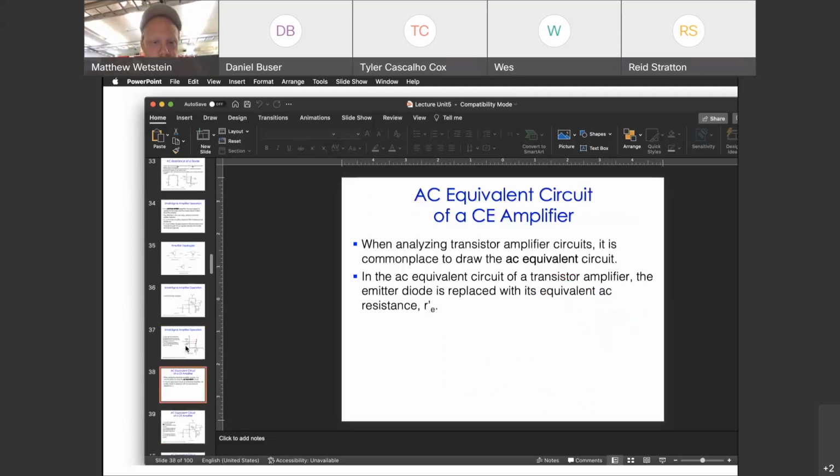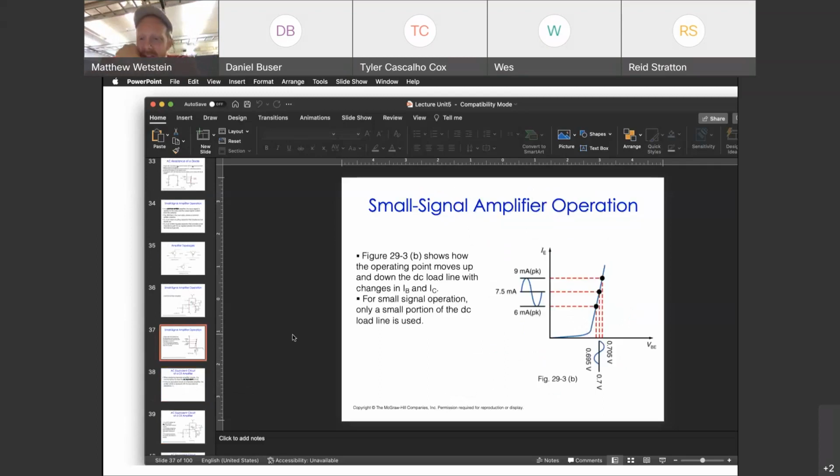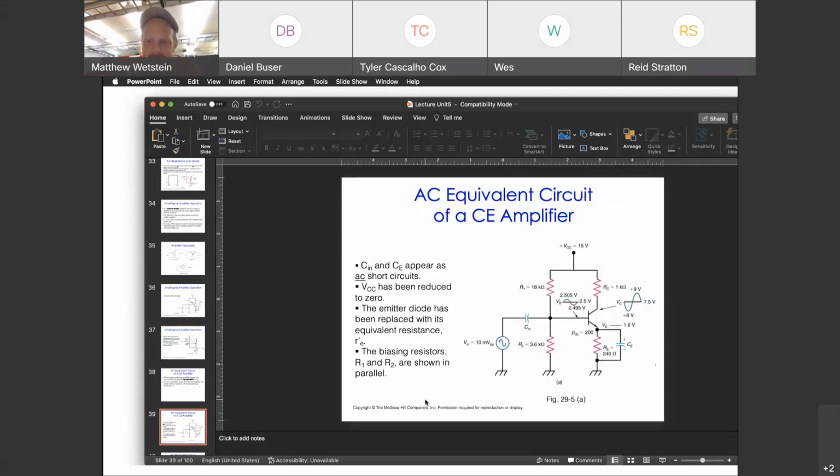So, in a sense, when you're dealing with transistor amplifiers, it's a similar phenomenon with diodes, where a small swing in voltage across a diode leads to a large swing in current. And if you have a resistor on that current, the resistor voltage will be large. And that's kind of what's going on here. This is your diode, your emitter collector region.